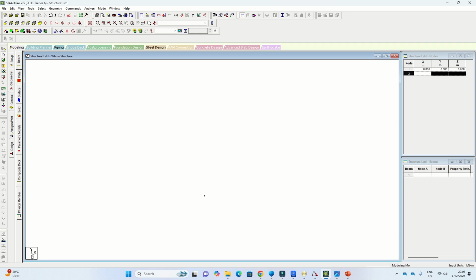If I'm going to move in the Z direction 2 meters, I will just have to select this node. For me to select nodes, I go to this left ribbon here. This is a node cursor. I'm going to select that one, then use it to select this node, destined red.